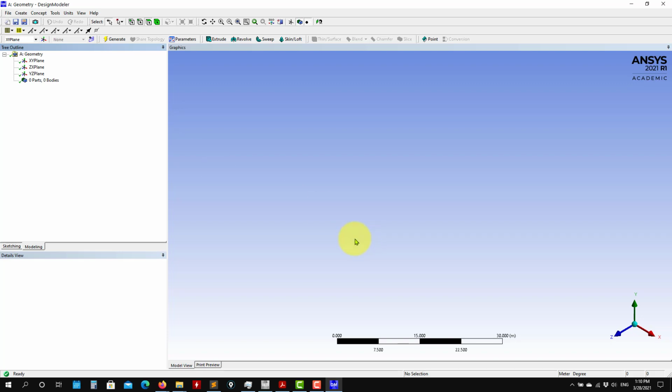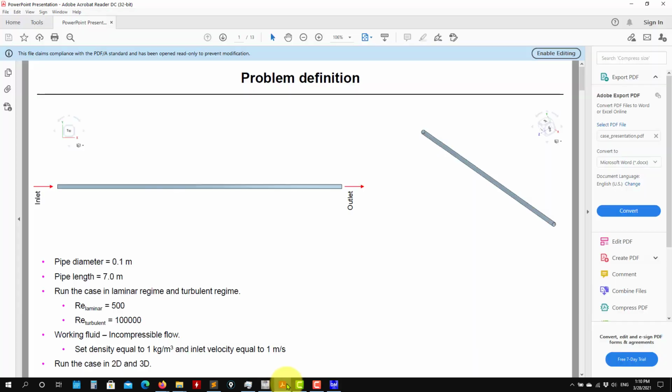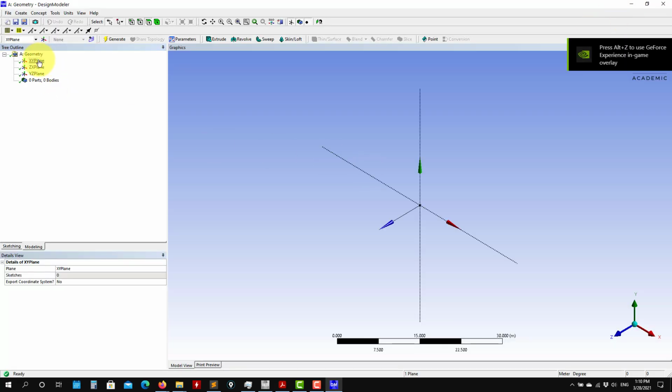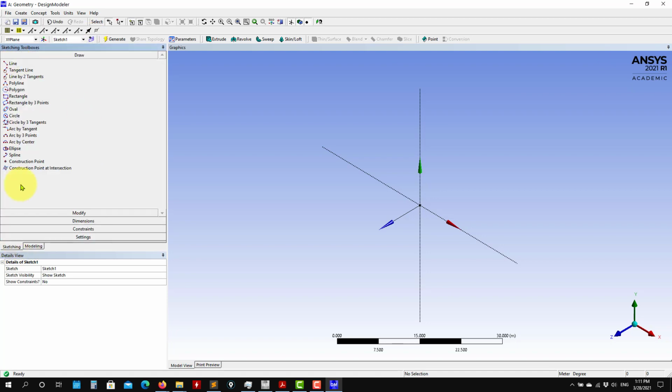Remember that to create a 3D solid, as I mentioned, you need to start from 2D sketches. Basically, what we have in this geometry is this pie, this circular section. So we can take this approach, create this profile, and then just extrude that profile. So let's do that. You choose a working plane. I will choose the one I would like to sketch on. You select this one, and you have new sketch, select, and now you have access to the